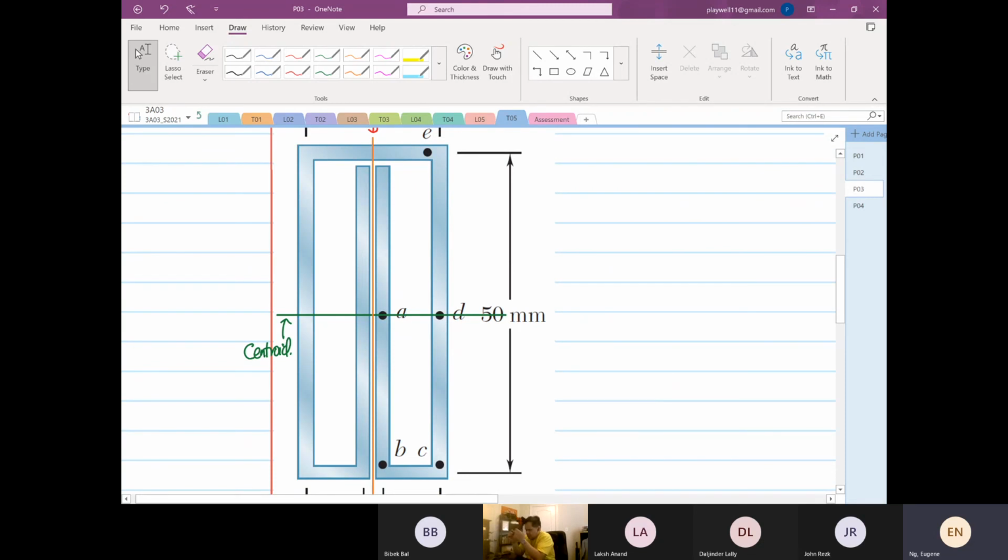So you ask me, Eugene, there are 4 webs down here. Which are the main two? The major web will always cover the top and the bottom of the structure. So I'm going to draw the shear flow of the major web. Okay, that is the shear flow of the major web.